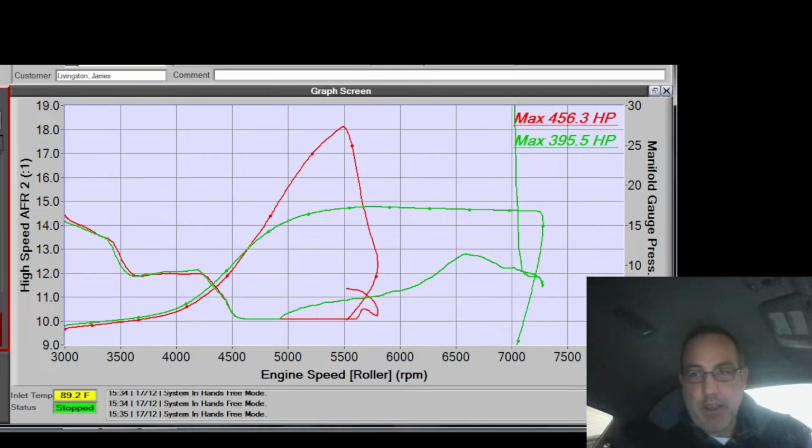Wow. Okay. Now, right there, you see it. You can see in the dynograph it went to 12.5 in boost. Luckily, the boost is only 16 pounds or so. Let me see what it was at. Absolute pressure, 32. So yeah, about 16 pounds-ish. Now if this was a Link or an M-Tron, they would have kept the fuel flat.